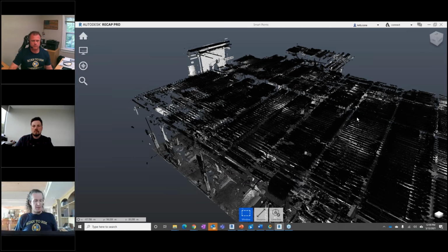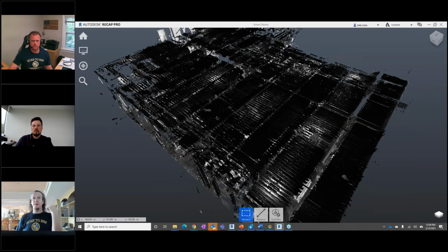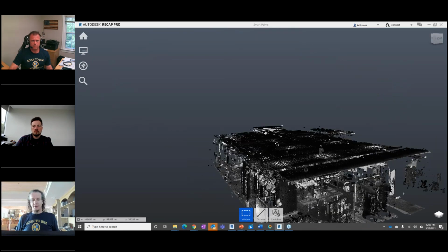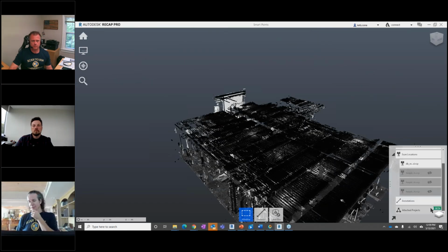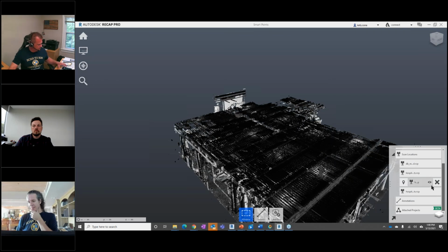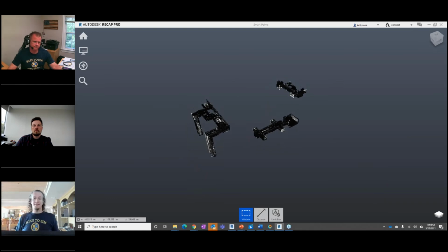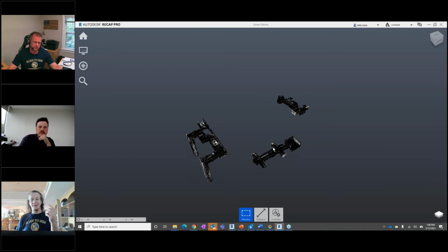things that we do to try and make life a little bit easier is we also, just like we talked about segmented meshes in Edgewise, we segment the point cloud, right? So this is a point cloud after everything has been extracted through Edgewise. Let me turn all the other ones off. So these are the point clouds that are just the piece of ductwork in this particular room. So, we get the ductwork, we don't model maybe the VAV unit or something like that and the grill, but you can see what that is. So it makes it real easy to pull all that stuff in.